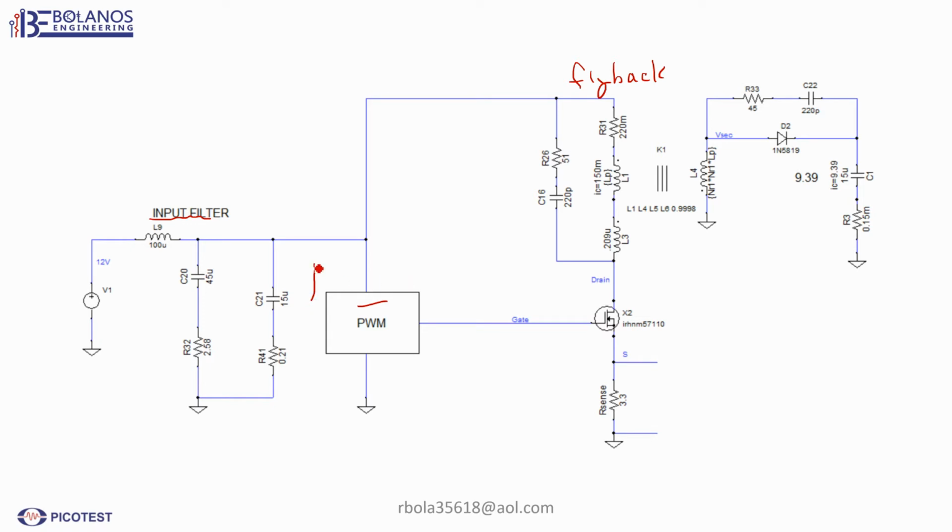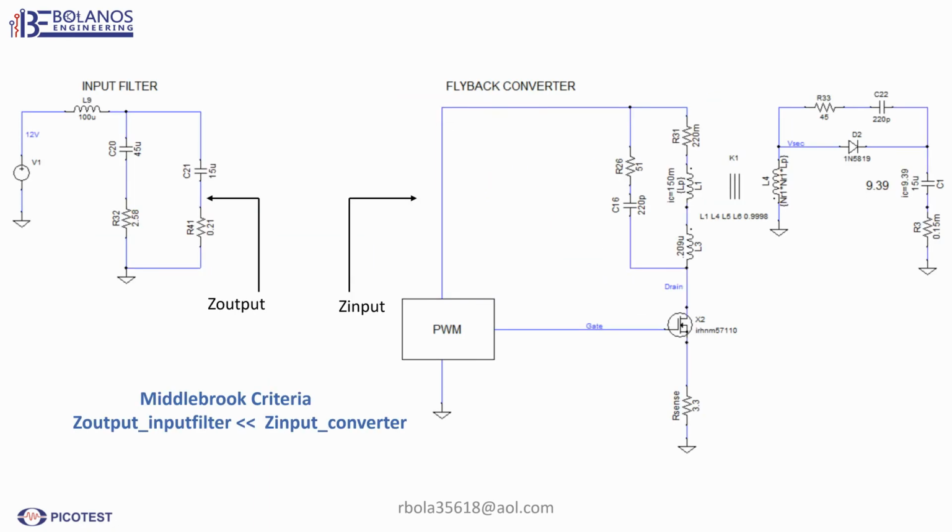The signal goes into this amplifier, I believe, and it's going to modulate this 12 volts. Now to make a measurement we need a voltage and a current. So we'll connect channel 2 to measure voltage.